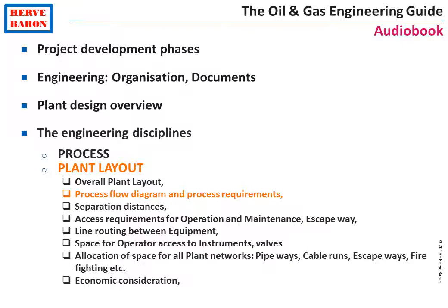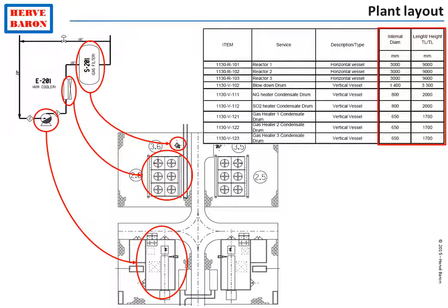Once the overall facility layout has been established, layout will define the unit layout. This is primarily done according to process requirements. The position of equipment is determined according to their sequence on the process flow diagrams. The size is given by process in the process equipment list, which shows the dimensions of the equipment which result from the process sizing. Such sizing, nevertheless, only concerns vessels.